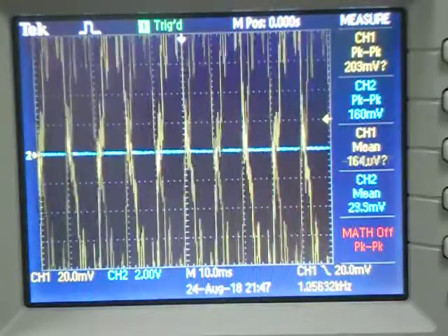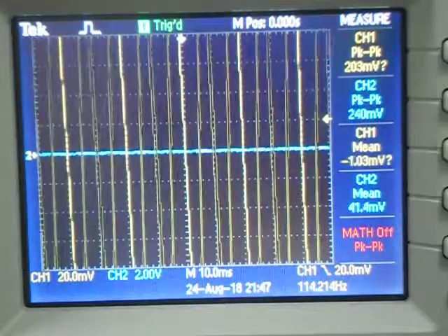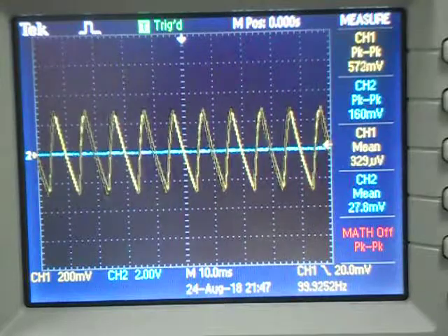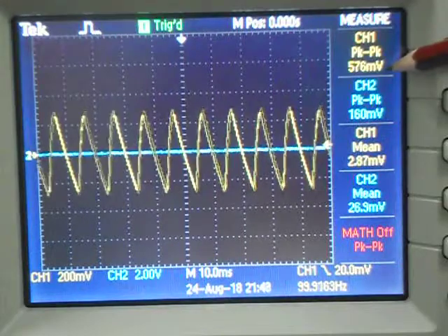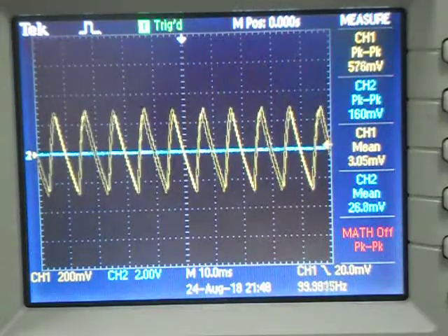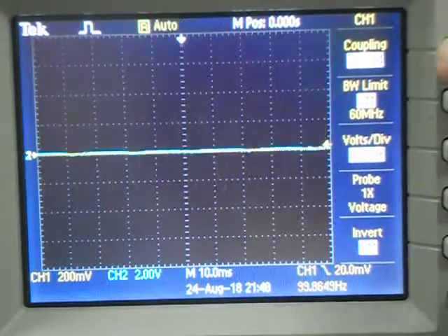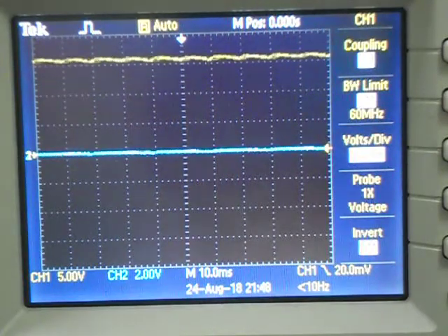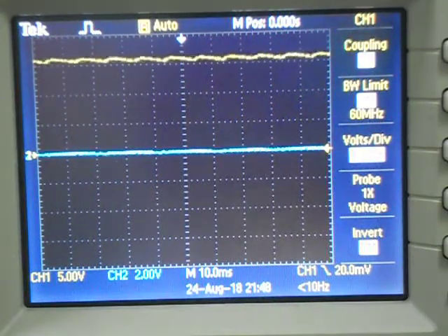And now if I measure my ripple, we can see that suddenly the ripple value has gone up by a substantial amount. On readjusting the scale, I can now measure it. It comes out to be about 500 or 550 millivolts, right? And if we see the DC of this output, again putting channel 1 into DC coupling, readjusting the scales, we can see that now we can already see some fluctuations on that DC, which was earlier quite flat.